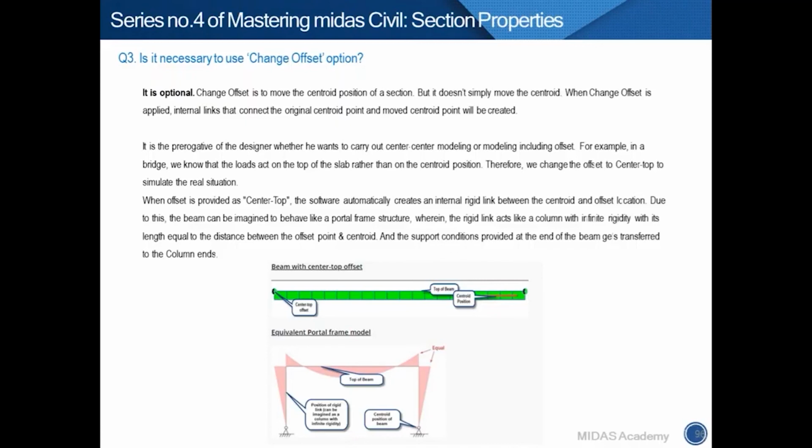So as shown in the figure, the software calculates the analysis with the internal structure condition. When designers build a model, they might have some assumption, like ignoring extra forces because they are too small. Change offset modifies the boundary condition and structure condition. They might face unexpected results depending on their modeling state. Therefore, I recommend using it on a case by case basis and checking the effect of change offset.